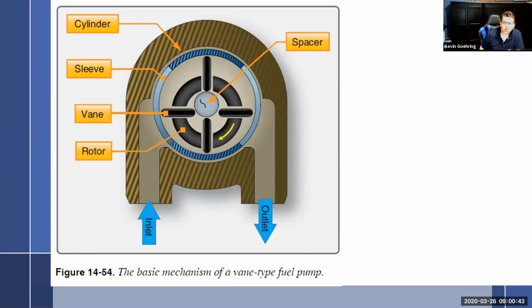Problem number two, what happens if this thing does shear and the shear shaft goes? Here's the inlet, and we have our boost pumps. Well, okay, this shears off and it stops and freezes like this. Then I run my boost pump, but the boost pump is going to boost fuel and it's going to come to right here and stop. So I have no way to get that boost pump fuel around.